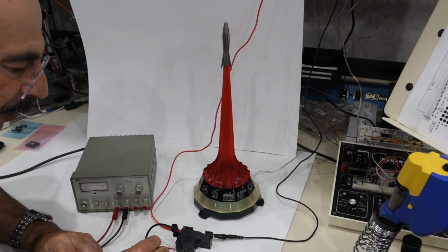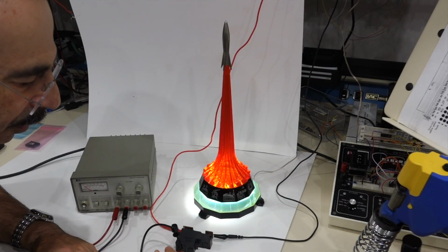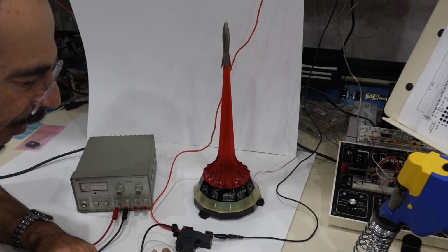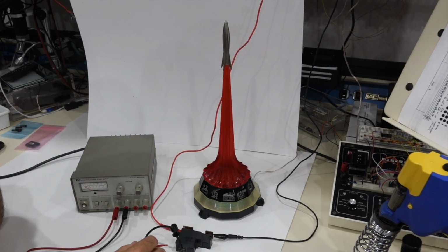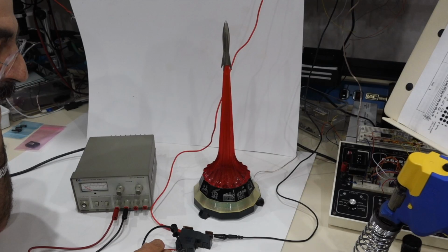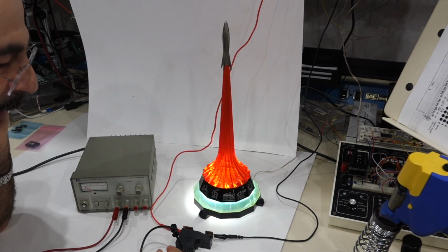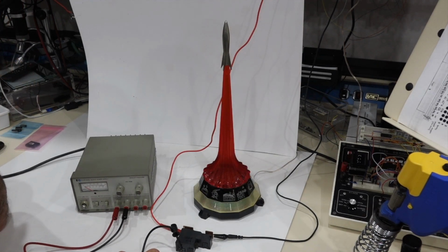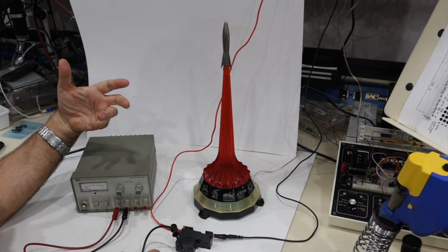If you energize the first coil, it turns it on. If you energize the second coil, it turns it off. So this thing has some kind of mechanical memory in it, because I don't need to keep it energized, right? I just give it a little pulse, it gets on, and I give it another pulse, it gets off. So it really solves several problems at once. So it solves the high voltage switching. It also solves the memory.